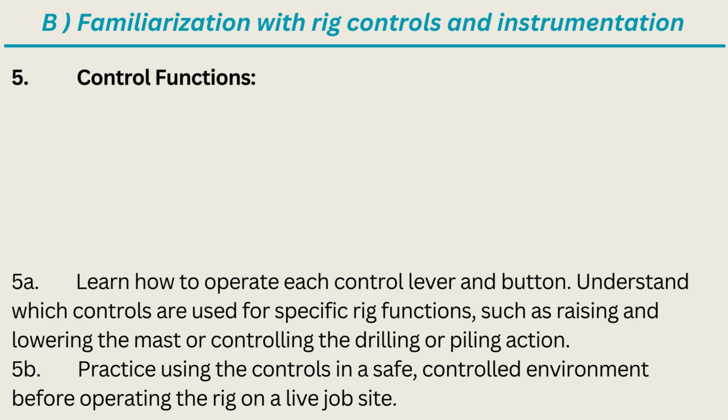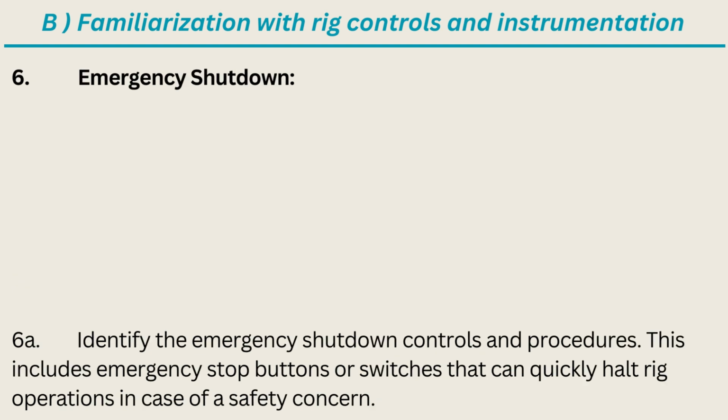Understand which controls are used for specific rig functions, such as raising and lowering the mast or controlling the drilling or piling action. 5B. Practice using the controls in a safe, controlled environment before operating the rig on a live job site. 6. Emergency shutdown.